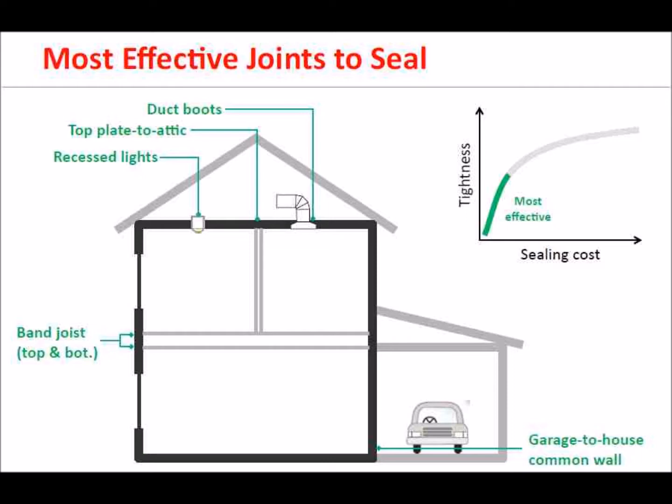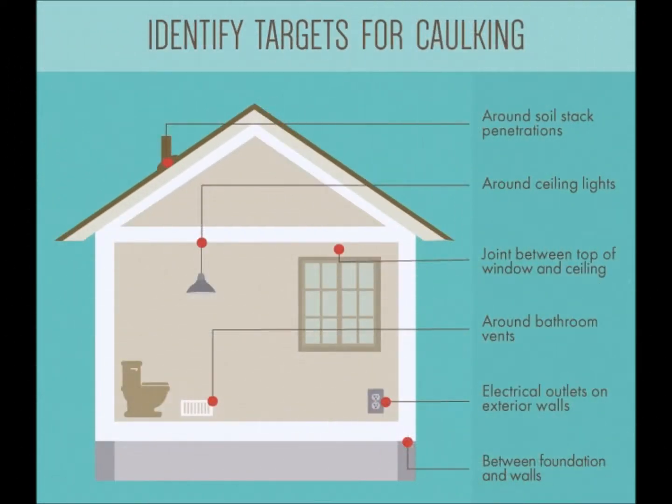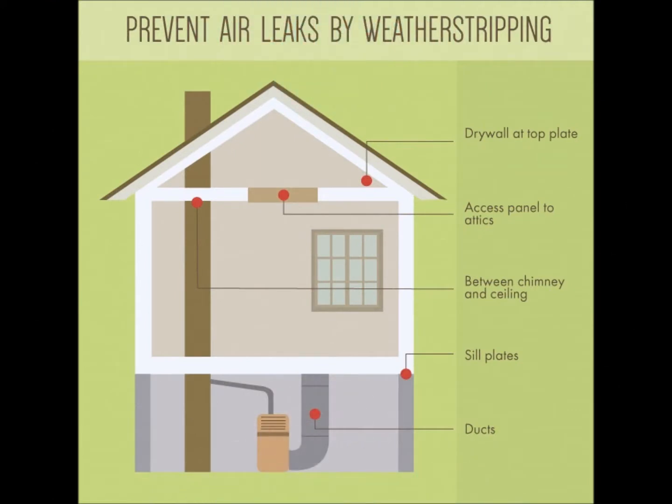What your client might not be fully aware of is that there are other pathways for air leakage, which include plumbing and electrical wire penetrations, openings or cracks where the wall meets the ceiling, any openings or cracks near interior door frames, any openings or cracks where 2 walls meet, gaps behind recessed cabinets, or around electrical outlets, recessed lights and switches, false ceilings or soffits in the kitchen, behind bathtubs and shower stall units, and through floor cavities of finished attics that are adjacent to unconditioned attic spaces.